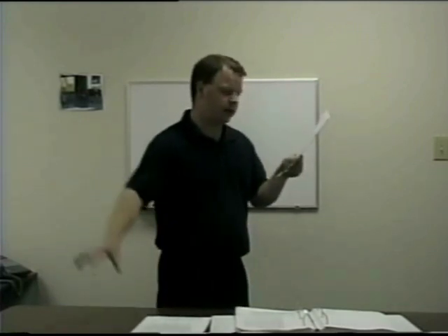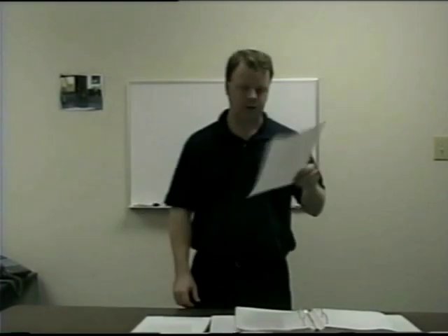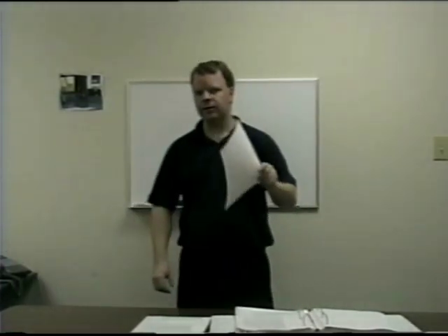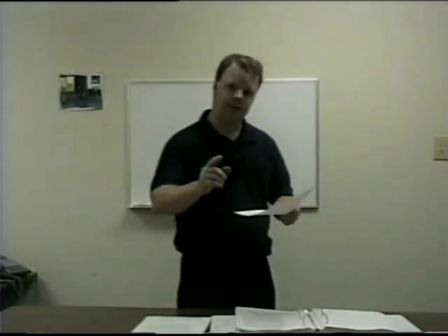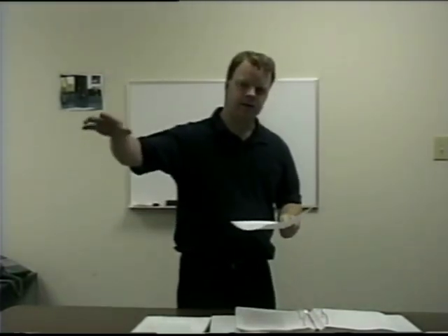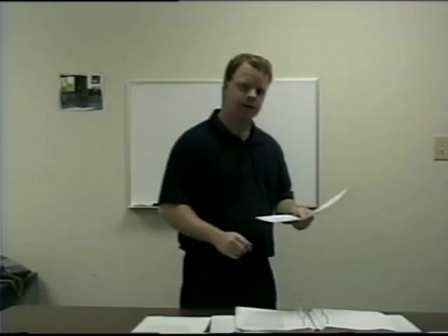Verify roll roofing is stood on end and kept free from contact with earth and moisture. Now look at that. There is a distinguishing mark. We're going to make sure that those roofers store their material as per standards. You see the ASTM standards and the FS standards. They tell us how the roofing material is to be stored. That roofer, he's used to working for Joe Blow contractor. He shows up and he throws his roofing material however you want. But when he works for our company, we're going to go out there and we're going to say that's not how that material is to be stored.